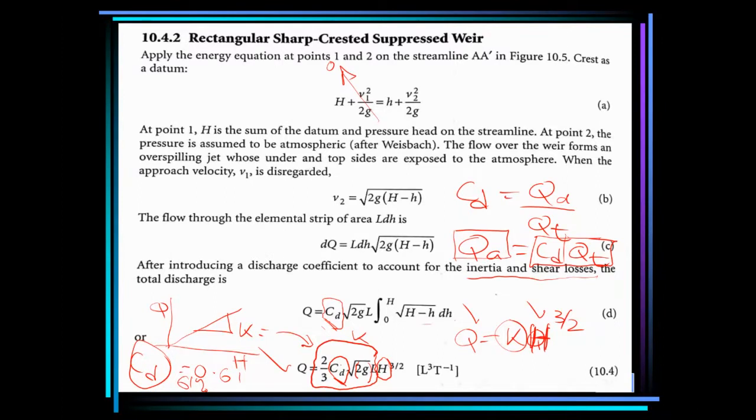But when we find the coefficient of discharge, it will help us to find the actual flow rate in the field, in which all factors are considered during the flow calculation. Because the actual flow rate is what you will get if you measure the volume over time. So that's the actual flow rate.